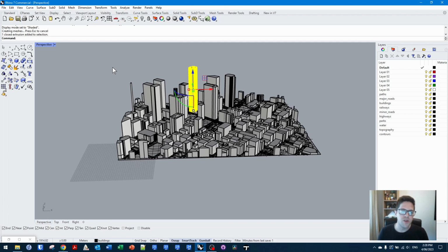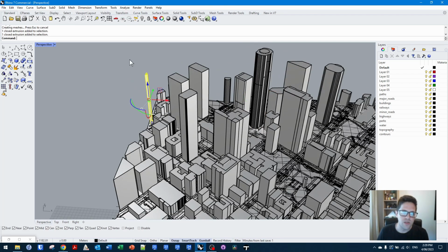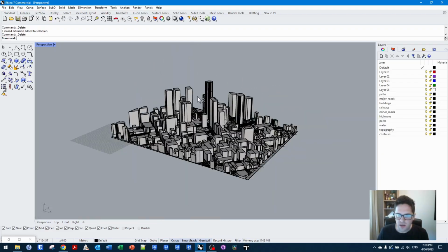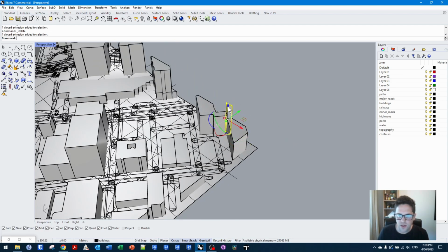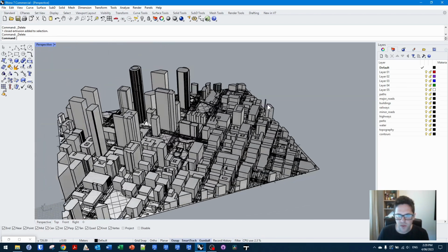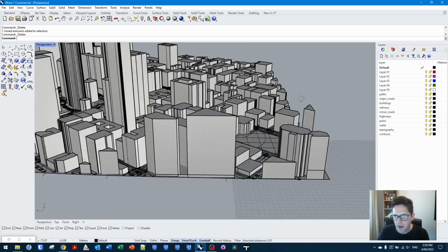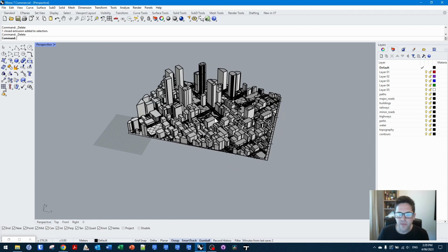Now you're going to need to be pretty critical when running sun studies. You may need more context than just this space. You might need to go to adjacent tiles and collect more buildings that may be tall enough to actually cast more shadow on your study. So for now, what I'm going to do is just delete a few little rogue edge buildings that aren't really needed, that don't really impact the study. You don't have to do this. I just prefer to do this so that you don't end up with some strange looking little tiny buildings if you happen to do a render of the space after. So that should do. So let's actually start cleaning up these elements.